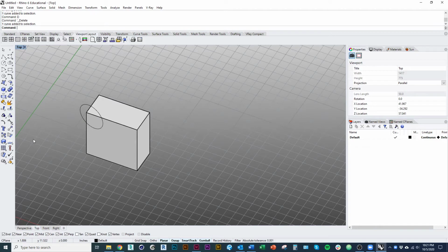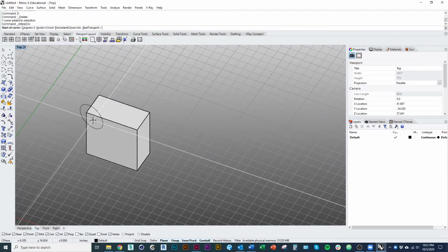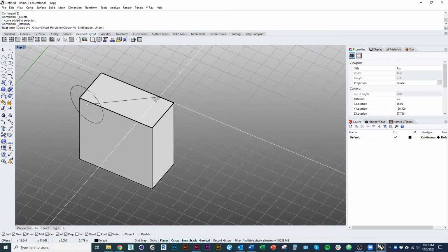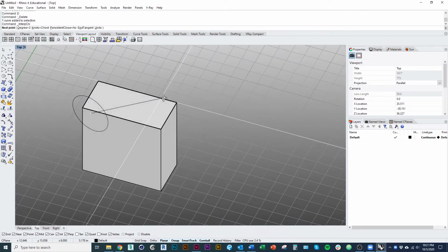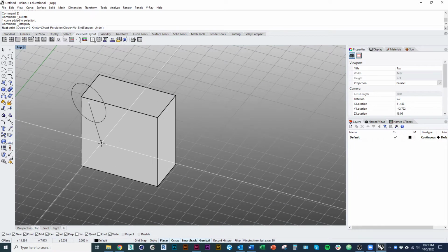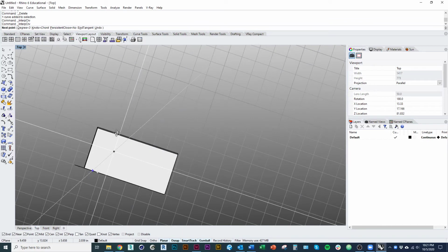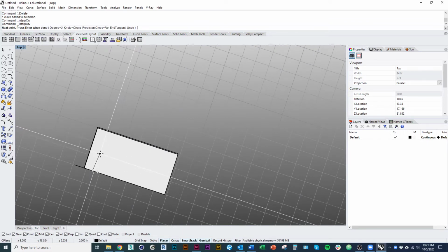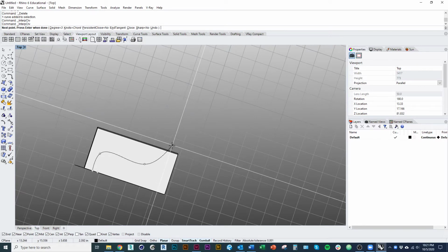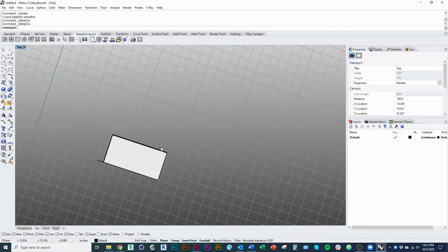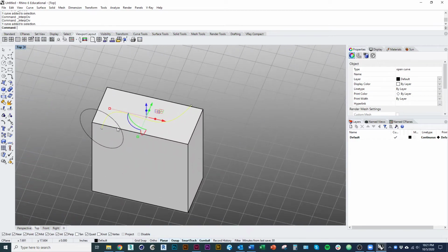But anyway, I'm going to use the spline tool, aka interp curves. Again, that's the thing that'll allow us to draw freeform curves. Now, I started at the center of my outline, so I got the center snap turned on. It'll ask me where's my first point. I'm going to snap to the center of my ellipse there. And now I'm holding Alt to not snap to anything in my object. I'm just going to draw it all the way through, just a pretty simple curve like that.